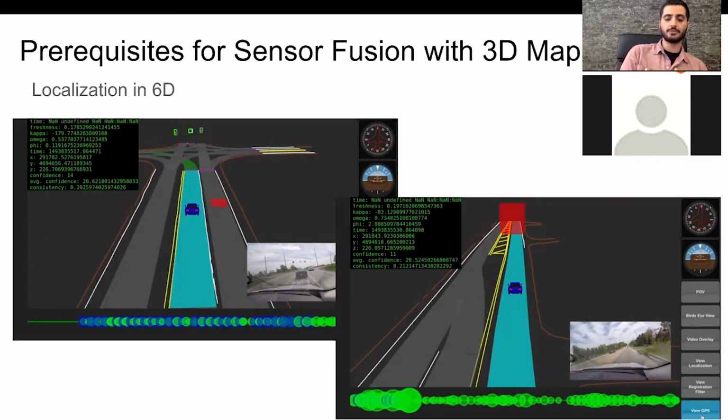In those two images, we're showing you in red a bounding box around where the GPS receiver and IMU GNSS solution thinks the vehicle is versus where the vehicle actually is, and that is done from our own localization and validated, if you at least want visually here, through the onboard camera. So as you can see, GPS can be in the next lane over, or it can be above the vehicle.